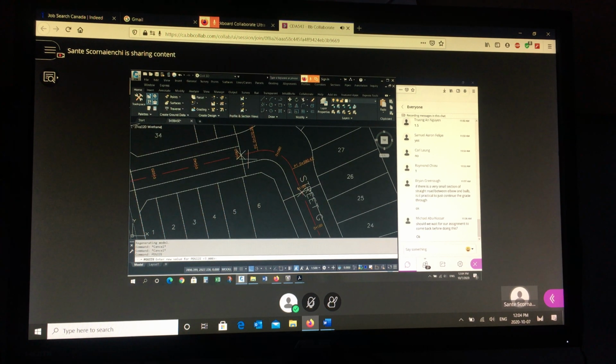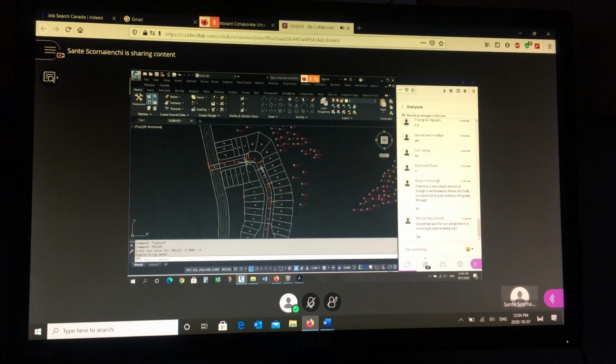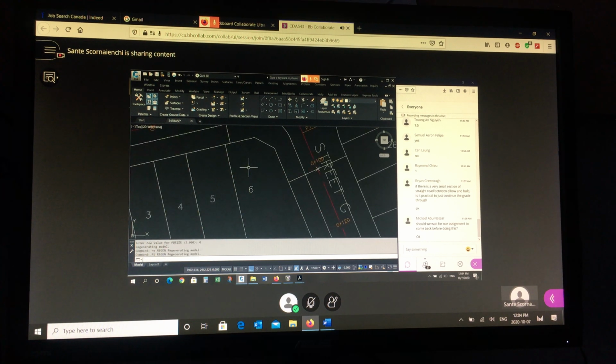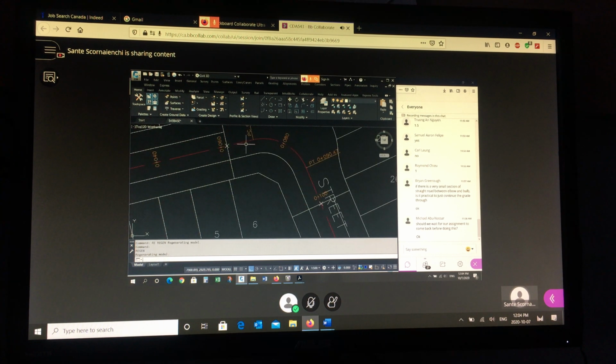And change it to something a little bit bigger, right? So 0, you're not going to see anything necessarily. Actually, 0 is, if you regen the screen, it's always the same size, so don't use 0. Give it an absolute number. So change the PD size to either 2 or 3. PD mode, I would suggest using a 2 or a 3. And then PD size, I would suggest anything bigger than 2 or 3. So you can change and manipulate the size of the AutoCAD point.